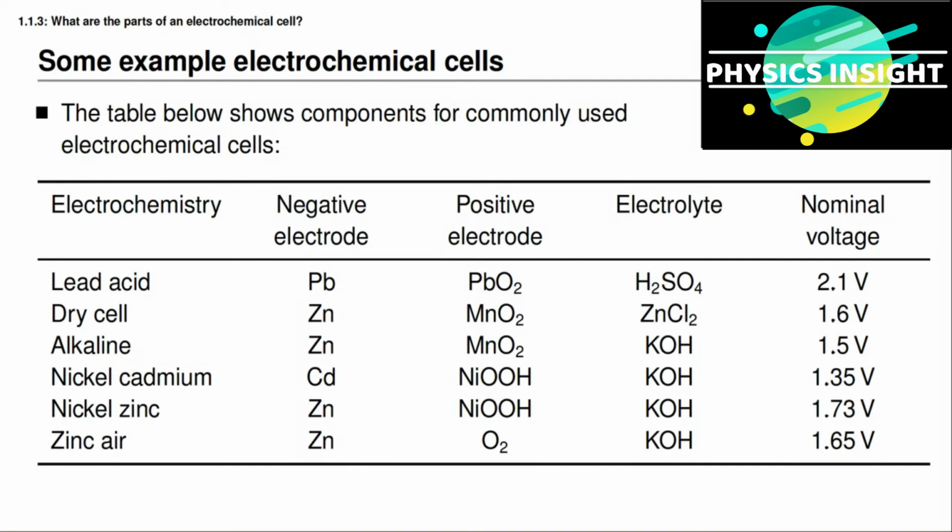Now, as you probably know, the voltage of a battery under load is less than the voltage of a fully charged battery cell that is simply resting open circuit. So the voltage depends on many factors, including temperature. And in the case of a lead-acid battery, it also depends on the concentration of the sulfuric acid used in the electrolyte. So you will sometimes see slightly different nominal voltages listed for a lead-acid battery cell in the literature, varying from around 2.0 volts to 2.1 volts.